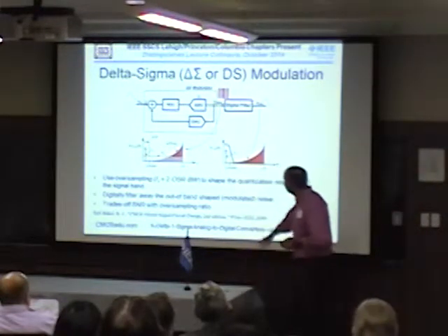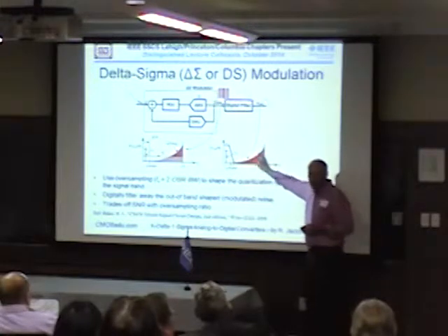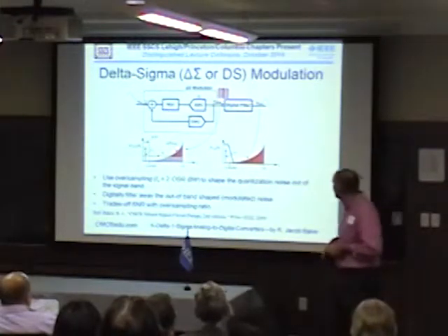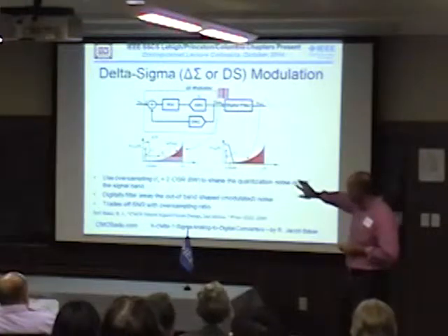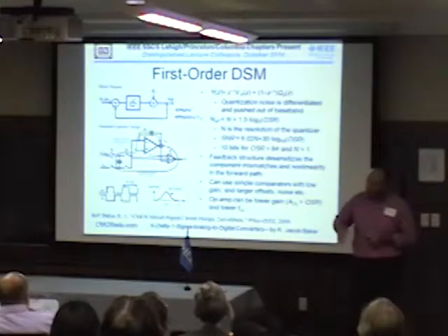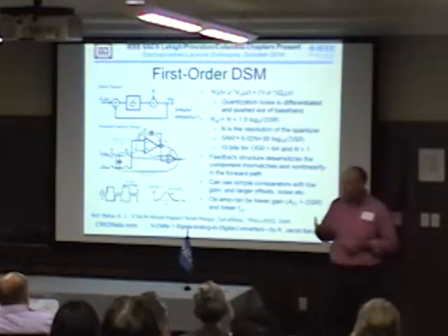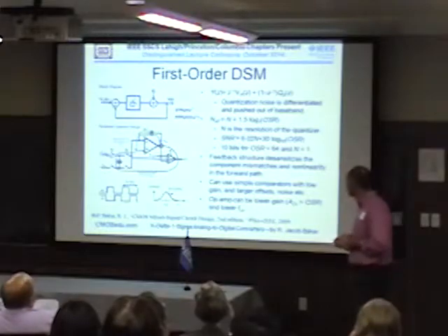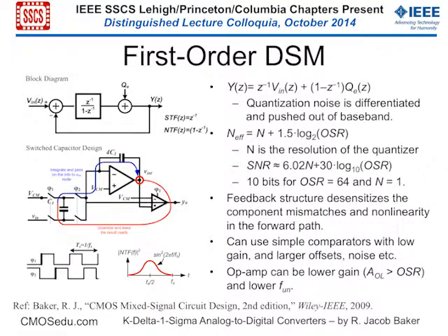And of course the noise doesn't magically stop here; it repeats because it's a discrete system. So we want to talk about this topology, how to implement it, how to modify it practically so we can get faster sampling. This represents a delaying switch capacitor integrator. I'm not going to go through too much of the details here, but basically here's your input signal. You sample the input signal onto this capacitor when phi1 is high.